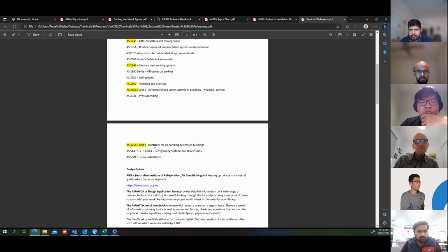4254 part 1 and 2, these are important. Ductwork for air handling systems in buildings. Part 1, I think, is for rigid ductwork, so metal ductwork. Part 2 is for flexible ductwork. That's worth getting familiar with. You need to be aware of what's in there.